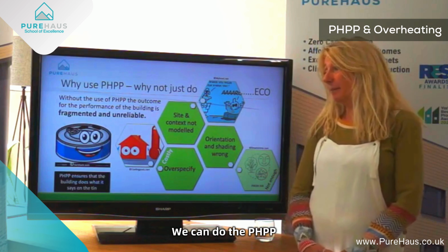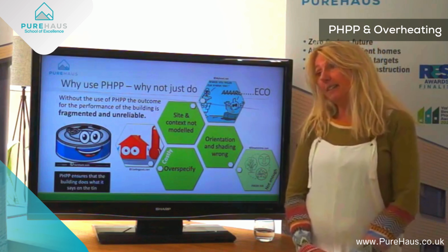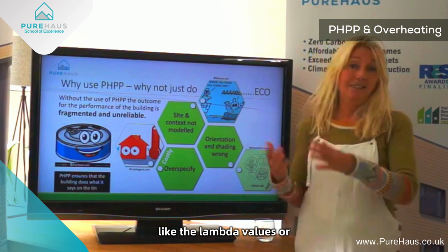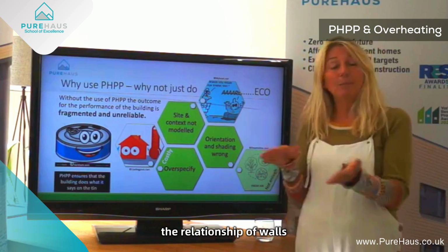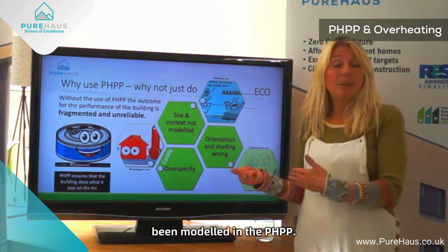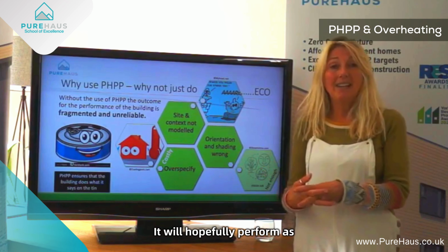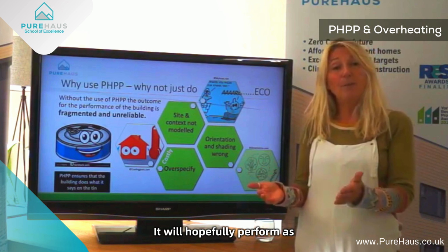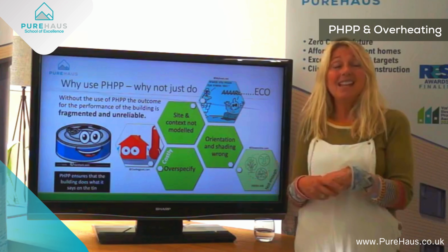We can do the PHPP, and provided everything happens as it's stated, like the lambda values or the relationship of walls to windows, provided it all happens as it's being modelled in the PHPP, it will hopefully perform as it says.